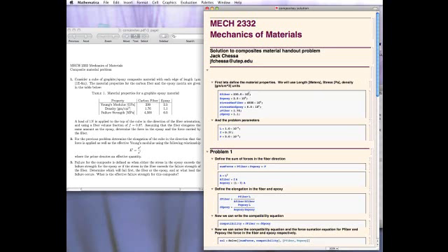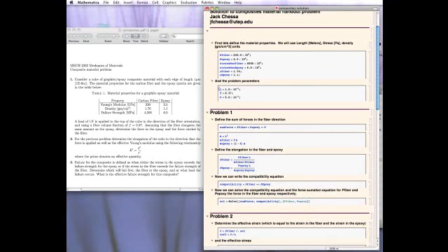So here's the Young's modulus for the fiber and the epoxy. Here's the maximum stress for the fiber and the epoxy, and here's the density for the fiber and the epoxy. That's just from the table given. We scroll down here, and then we define the length of an edge, the volume fraction, and then the load applied. So here's the one that I knocked down to 5 times 10 to the minus 3rd. Okay. All right. So those are the problem parameters.